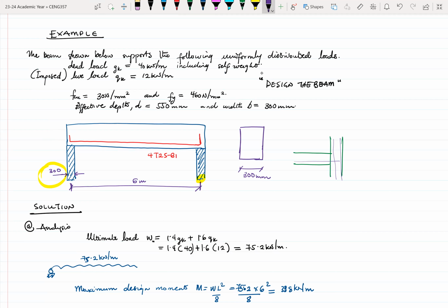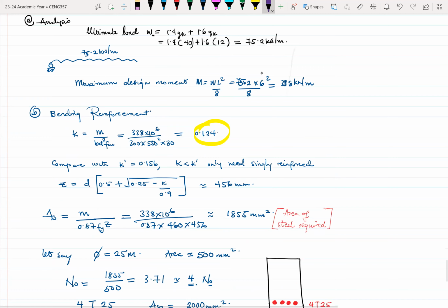Okay. And again, tension reinforcements at the bottom are for the spans. They're typically not for the supports. So generally, we curtail how much of the rebar gets to the supports. Okay, so I'm going to write that over here.